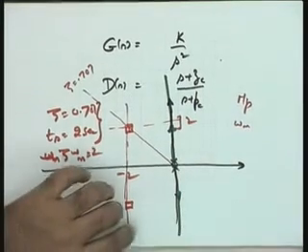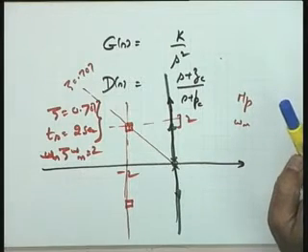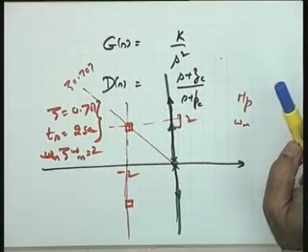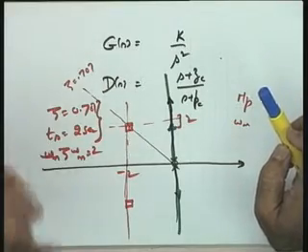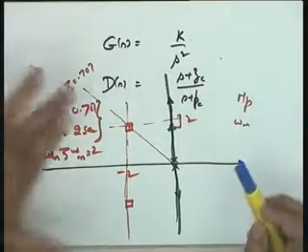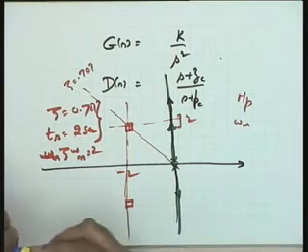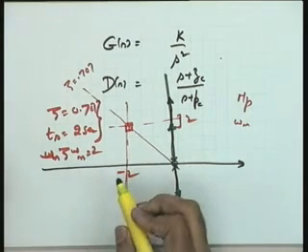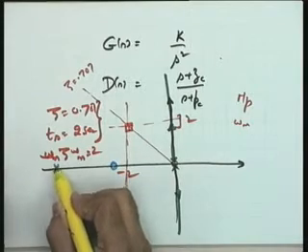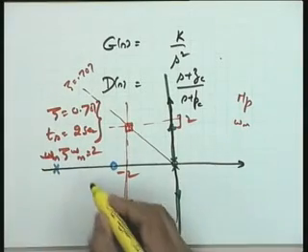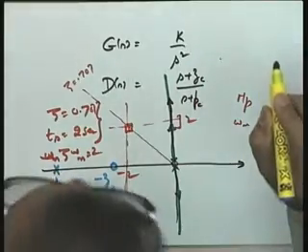Any suggestion, please? On the basis of discussions we had, what do you suggest? A PD compensator means, first of all, trying to place a 0 somewhere suitably. You have to place a 0 and a pole. So once you have translated this into these closed loop poles, the other primary step in the design is to place the 0 and the pole. Let me tentatively place it here. Let us say minus ZC and minus PC. I do not know their locations.